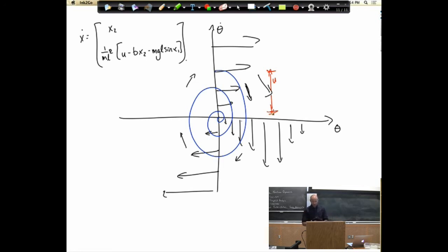You can imagine now what underactuated is all about, right? If this is a high-dimensional vector field, let's say I have a robot with 4 joints. I have a plot that would be in 4 positions and 4 velocities. And let's say I have only 2 control inputs u, then the way I get to reshape that vector field is constrained in subtle ways, right? And so taking that same vector field and bending it to your will and making it do the right thing gets to be a harder problem. But if we can throw the right computational tools at it, we're going to see that there are still very, very satisfying solutions. Yeah?